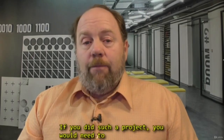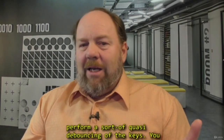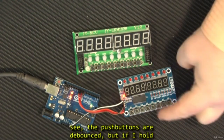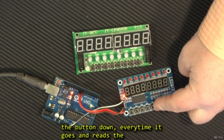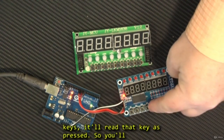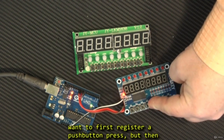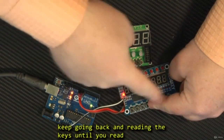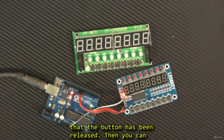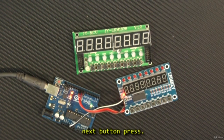If you did such a project, you would need to perform a sort of quasi-debouncing of the keys. You see, these push buttons are debounced, but if I hold the button down, every time it goes and reads the keys, it'll read that key as pressed. So you'll want to first register a push button press, but then keep going back and reading the keys until you read that the button has been released. Then you can proceed to read the keys looking for the next button press.